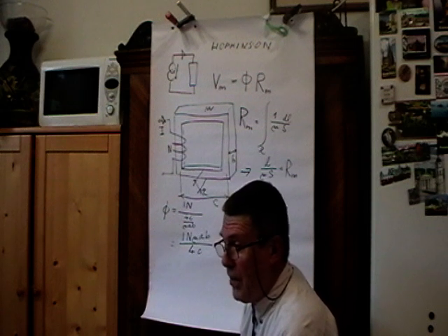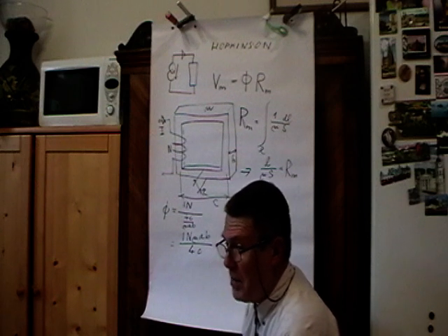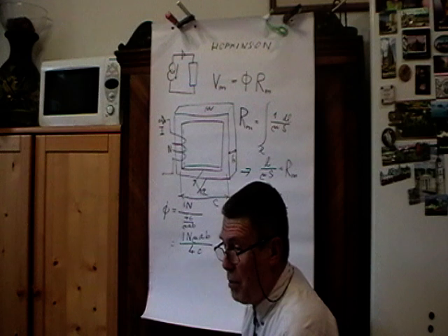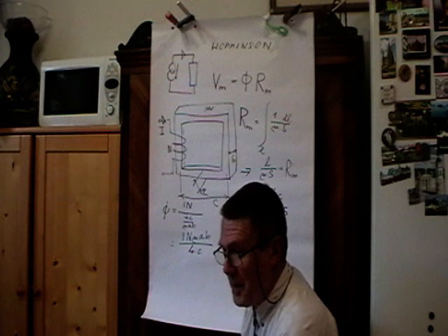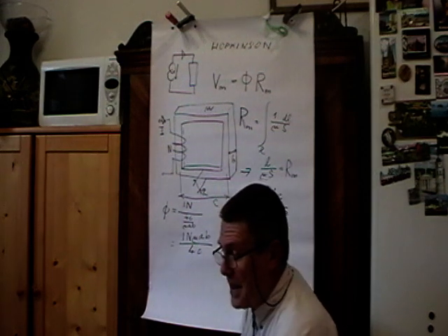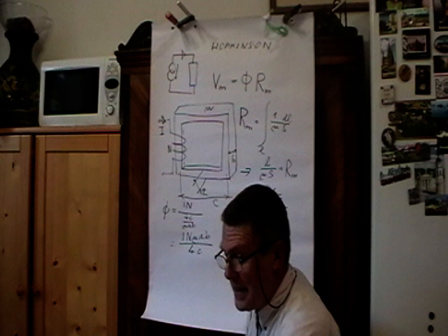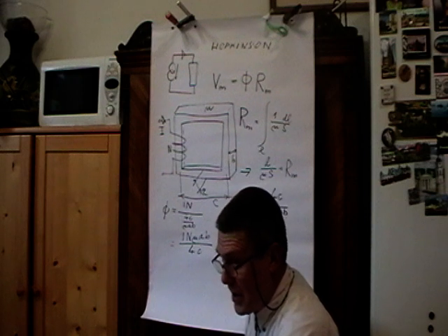So what you can really use with steel compounds is up to 1.4 Tesla. So this gets us some information about available magnetic fluxes in the core of certain cross-section.